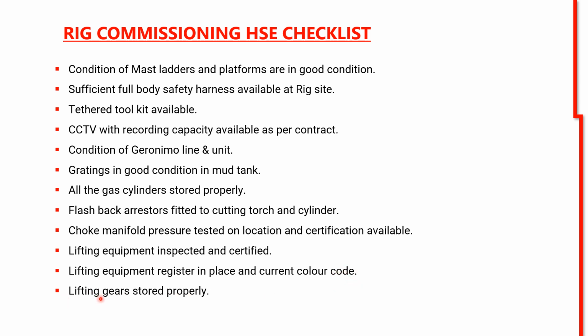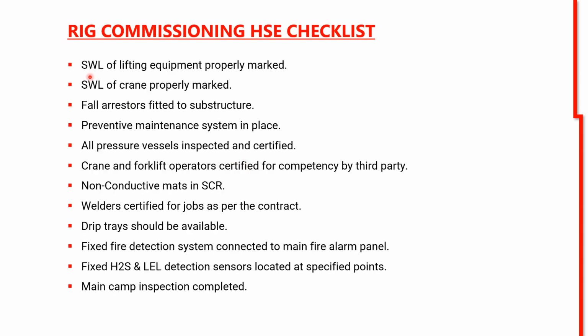Lifting gears stored properly. SWL, safe working load, of lifting equipment properly marked. SWL of the crane properly marked. Do you understand what it is telling? In all the lifting equipment, whether it is a lifting belt, a shackle, or a block, the SWL of that specific piece of lifting equipment should be marked on that equipment. SWL of the crane should be marked on the crane itself.